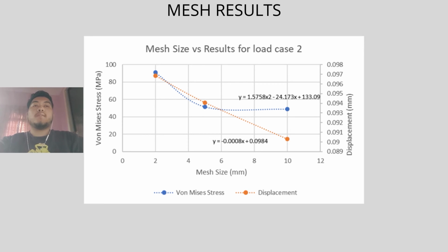It clearly shows from the graph that a finer mesh will evaluate greater stress, and this depicts that a fine mesh might represent the local stress concentration patterns in a zone close to the load application. That's why a fine mesh is always chosen for the analysis.